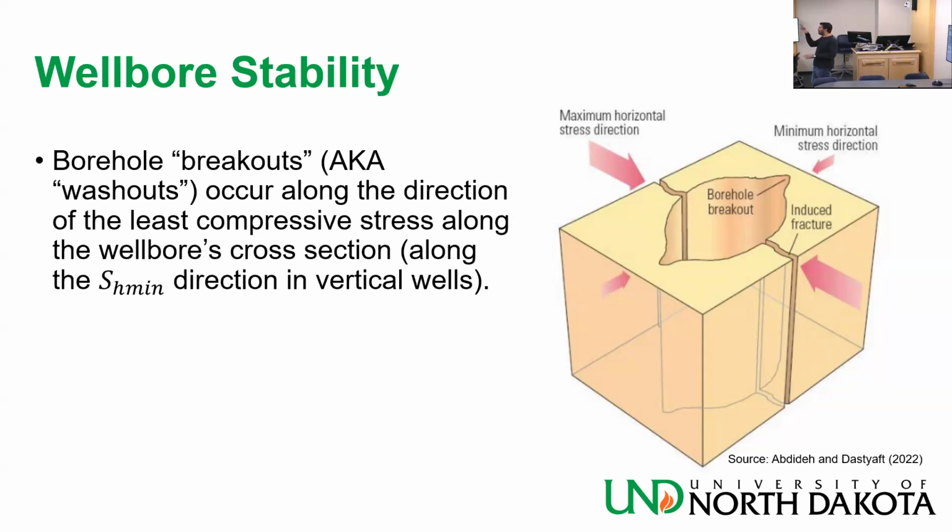I have imperfections in the way I'm drilling a hole. Sometimes my mud weight is a little bit too high, sometimes a little bit too low. It alternates. This is manifested on the borehole walls as washouts if my mud weight drops low, or drilling induced tensile fractures if the mud weight is a little bit too high.